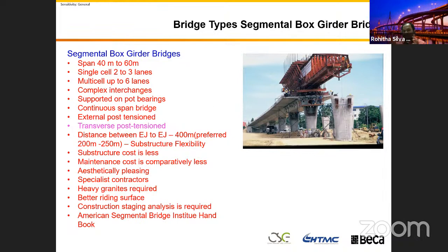But please remember, this manual is developed for the AASHTO standard, and you have to modify it according to the standard you use. In Sri Lanka, for example, they use the British standard and Eurocode, and in Australia we use the Australian standard. The live load on bridges is significantly different. I will make a comparison when I discuss bridge loading, so you can get some understanding and insight about it.